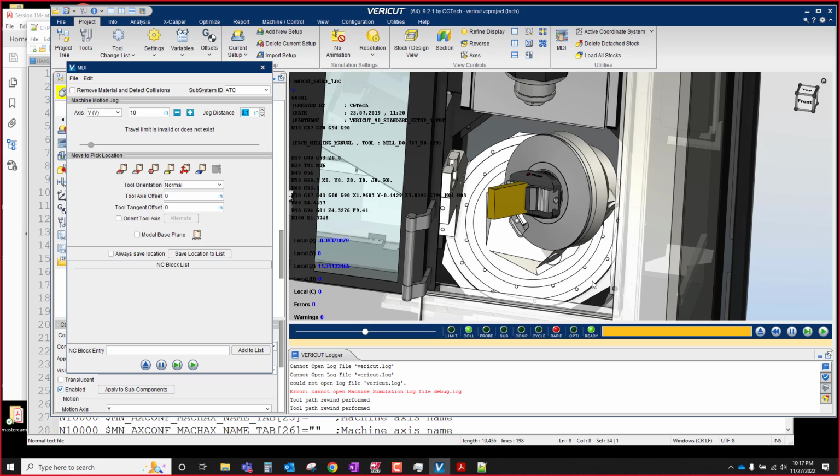So it would load the pallet in, it would scan the blade, and the machine would sit there for 8 minutes while this process kicked off in the background. As long as everything was copacetic, it would automatically load that NC file and machine the blade. The machining would take 15 or 20 minutes, depending on which blades they were running. Then it would kick it out and repeat all over. You figure it took roughly a half an hour to do one. As long as there were no problems with the file, that whole process was running for over 12 hours unattended. So that's 24 parts, as long as there were no errors.